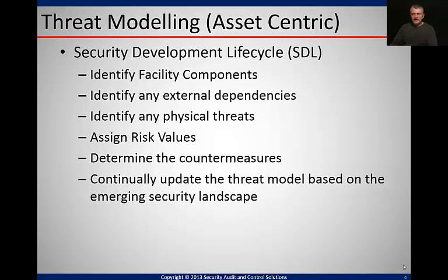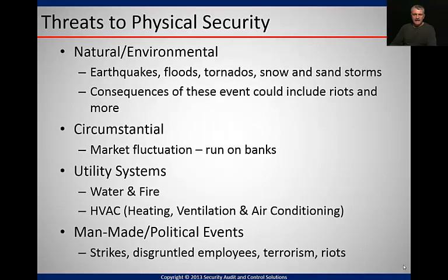Now, as part of an asset-centric environment, we need to look at threat modeling. A security development lifecycle, or SDL, includes the following steps. We have to identify all the facility components. We have to identify any external dependencies on those components. We have to identify any physical threats to the components, assign a risk value, and determine any countermeasures that we should apply and have applied, and that will give us our inherent and resultant risk. We need to do this continually to update the threat model based on the emerging security landscape.